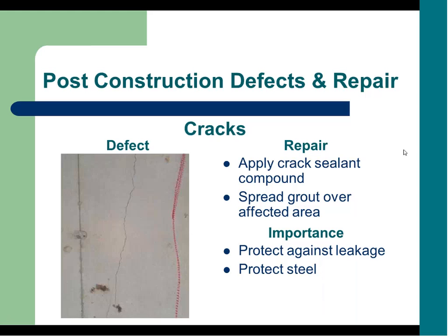So it depends on the engineer's spec. As long as the fiber is prescribed in the concrete mix itself and it meets our standard, which is in the checklist, I can try to pull that up at the end if we want, we are not requiring it throughout the floor. I have seen where they do. It depends on the preference of the engineer, really. We do require the reinforcement always in the columns, footings, and in the floor footing. So it's basically a requirement in the type of concrete and the load that it's going to be taking. If someone needs more specifics on that, I can sure go in that direction.